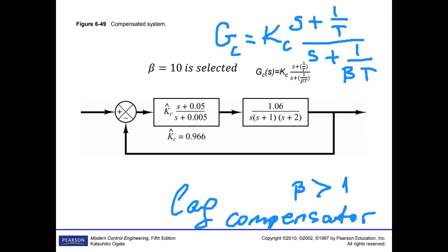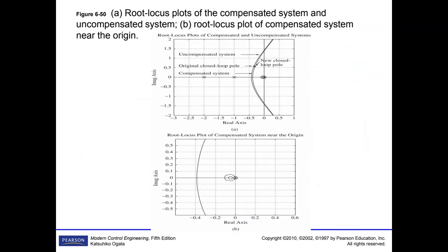And you can see here that we are adding a zero and a pole. The pole is very near to the origin, and the zero is also very near to it. It's obvious that when you add those here, your curve is not changing. What's actually happening is that the pole and zero couple here without changing the curve. That is what a lag compensator is all about.